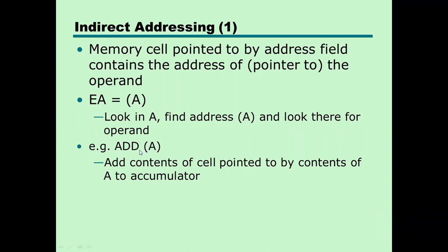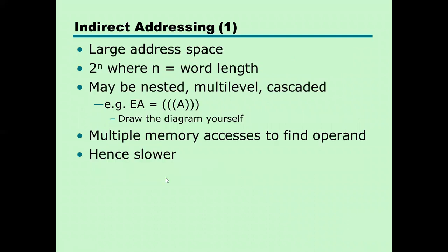So this A register will have the address from where the operand is located. Let us understand this with an example, add A. Here we are performing the operation of addition. We are adding the number, but this A is not the operand. This A is the register which is holding the memory address. That will be clear in the next slide. Can you see this?